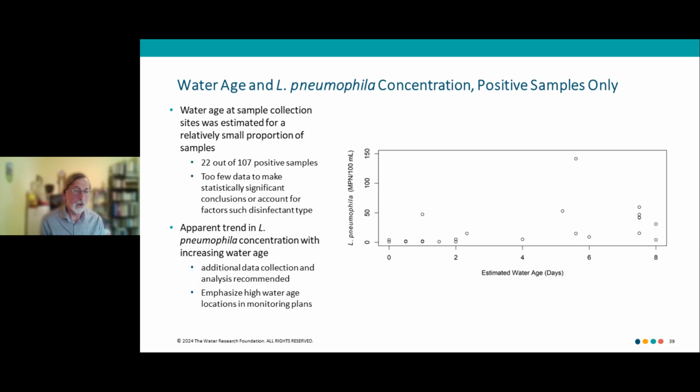What type of pipes are in the distribution system in the vicinity of the sample collected? What's the disinfectant residual there, et cetera? In future studies, hopefully people will be more successful than we were in getting the water age data, and monitoring really should emphasize high water age locations.